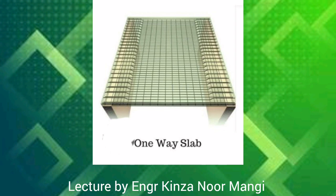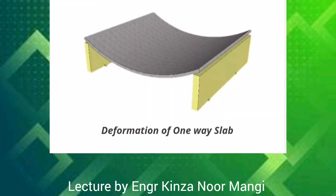In one-way slab, the slab is supported by a beam on two opposite sides only. In a one-way slab, the load is carried in one direction perpendicular to the supporting beams. In a one-way slab, bending is only in one direction, that is in a shorter span. The deflected shape of one-way slab is cylindrical. The examples of one-way slabs are cantilever slabs, chhajas, and verandas.